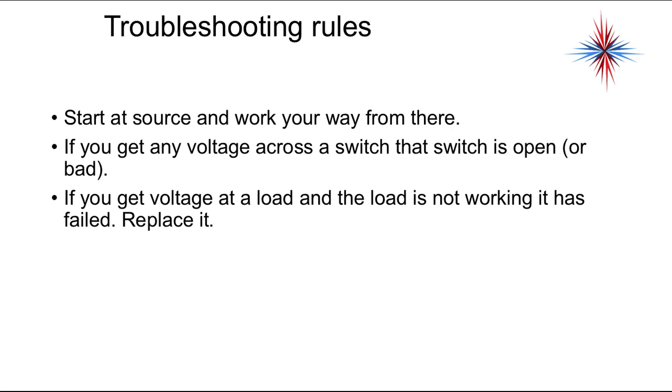When you're working with a meter, be very, very careful about where you're putting your hands and how close together you're putting your meter leads, especially the metal ends. They can arc and they can cause a short circuit. If you touch one meter lead to voltage and touch the other meter lead to the case of the equipment, that meter lead is live. You could really get hurt by voltage being on that case. So again, just be very careful where you put things and where you put your hands.